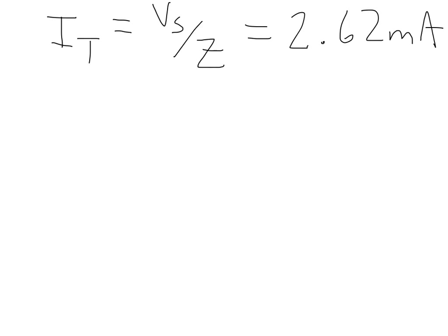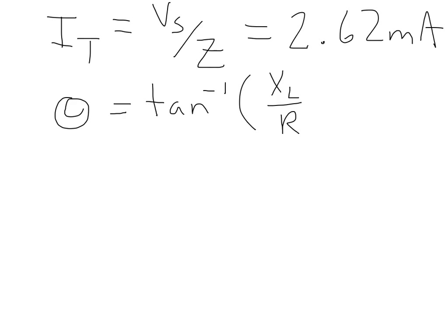After calculating the total current, I can calculate the phase angle of the circuit. The formula for phase angle is the inverse tangent of the inductive reactance divided by the resistance of the circuit. So using my calculator, I'll take the inductive reactance, which is 2,694.12 ohms. I divide it by the resistance, which is 2,700 ohms, equals. Then I'll take the inverse tangent, and I get 44.94 degrees.